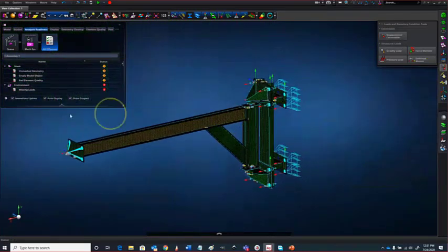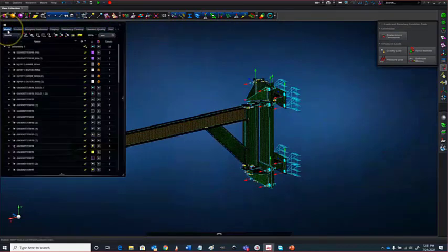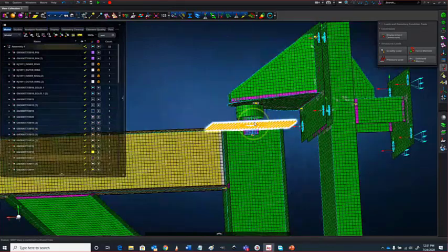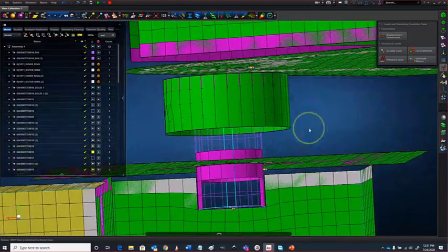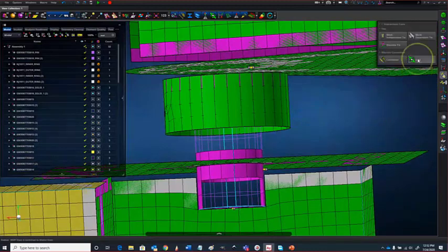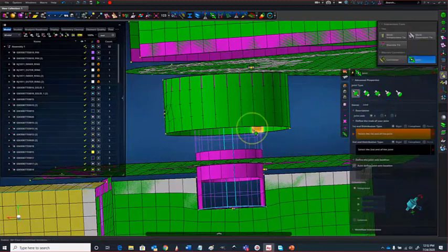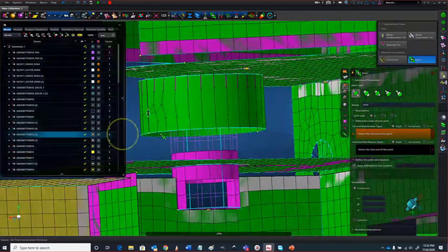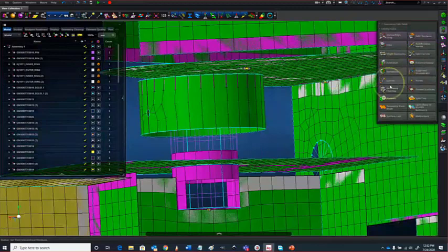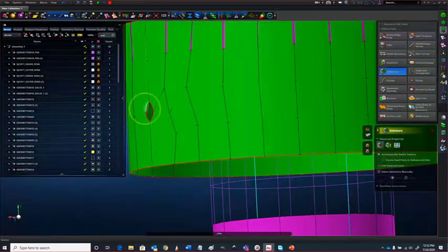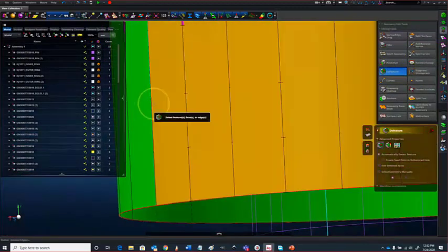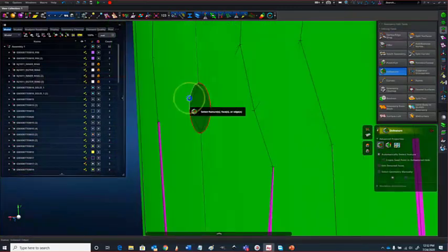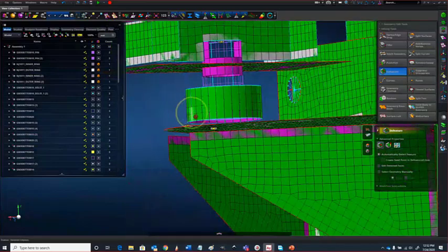I'm going to run a modal analysis first, just to check whether the joint connections are correct. And I've just realized I haven't created them. So let's quickly create joints. And for the purpose of this exercise, oh, there's a little feature that I've missed that I don't need, suppose it's the hole for the grease.